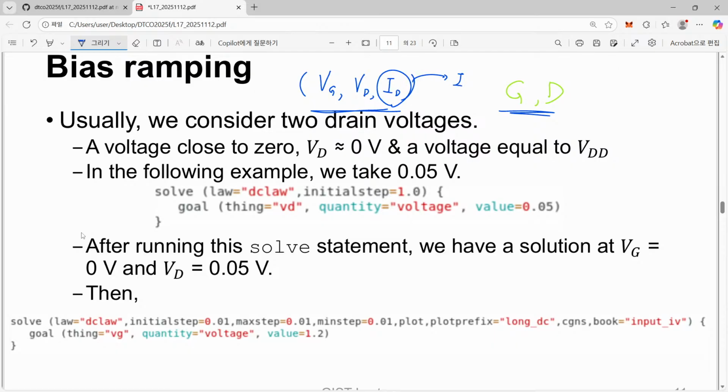Source current is just a minus of drain current, quite similar, and we assume that gate current is quite close to zero, and also our substrate current can be small. So of course we have a certain amount of current. However, it can be regarded as just reverse current of source body junction and drain body junction.